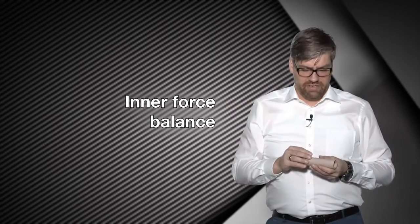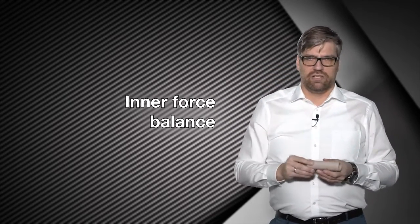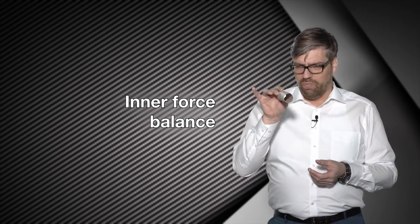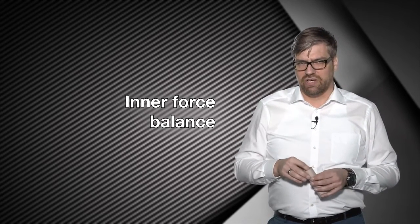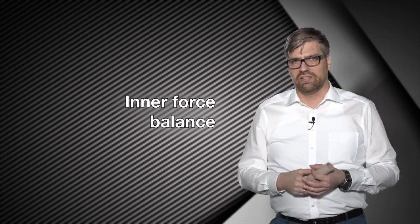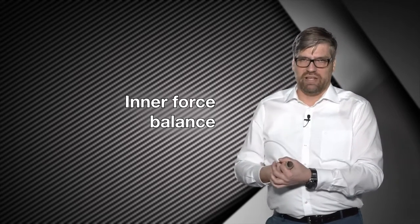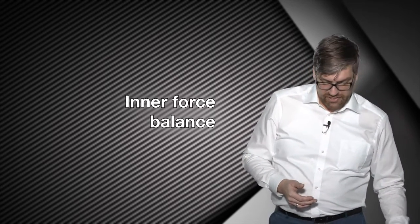The load carrying capacity decreases significantly just by applying this cut. And by applying this cut, I prevented the structure from using this inner force balance, and this is a responsible factor for this very, very bad structural behavior. So the rule is you have to use the inner force balance.